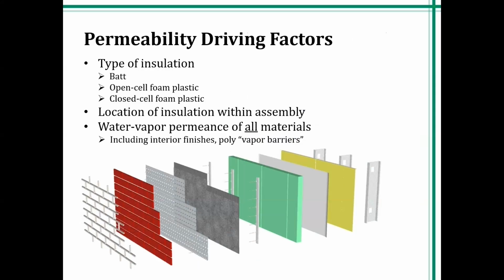And that's usually on the outermost face of a wall. I don't know that there would necessarily be any need to have an additional air barrier. I have had architects want a redundant system in the event that the insulated metal wall panel systems were to experience a failure. And specifiers on a couple of projects I can recall specified a permeable air barrier in the event that the IMPs, I think they abbreviated them, were to fail. We still have a plane of airtightness underneath that insulated metal wall panel.